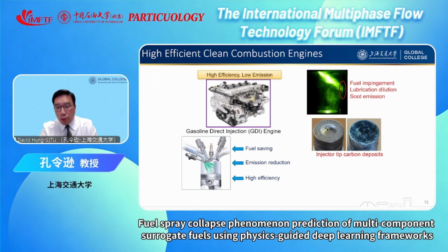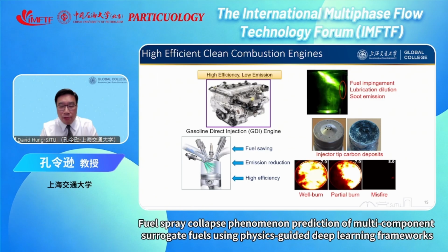That means the fuel spray coming out is quite different from the ideal condition after the vehicle has used this injector for, let's say, 10,000 kilometers. With that, we can have well-burned combustion characteristics, a partial burn, or even a misfire with no combustion cycles. This is a very challenging problem, and it takes many people to come up with different solutions.